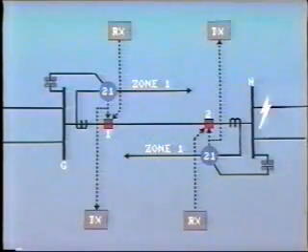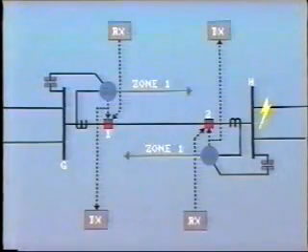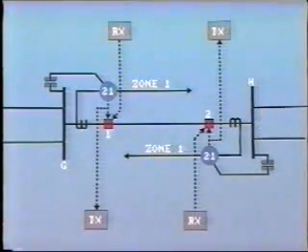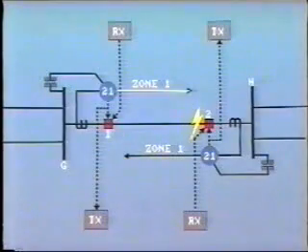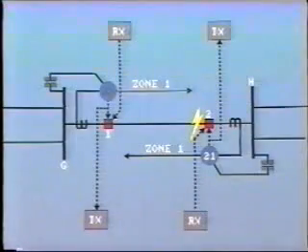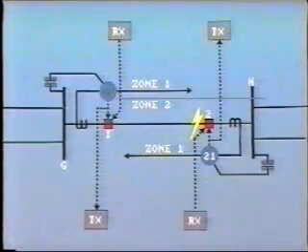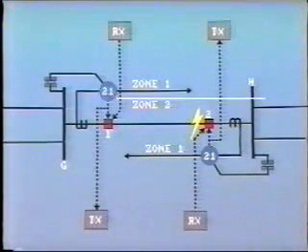If the fault is external to the line, we do not want the relays to operate. Therefore, directional relays must be used with the tripping direction looking into the line. So this provides selectivity. Now let's look at a fault in the last 20% of the line. In this situation, the Zone 1 element of the distance relay located at bus G, let's call this station G, will not operate. The fault is outside of the preset zone. The Zone 2 element detects the fault, but tripping of breaker 1 is delayed.